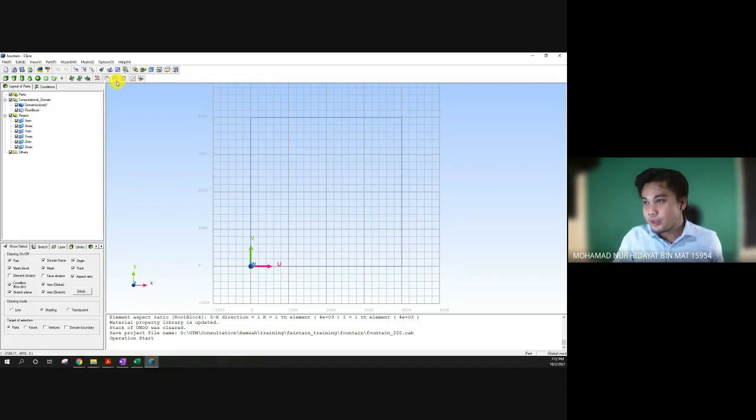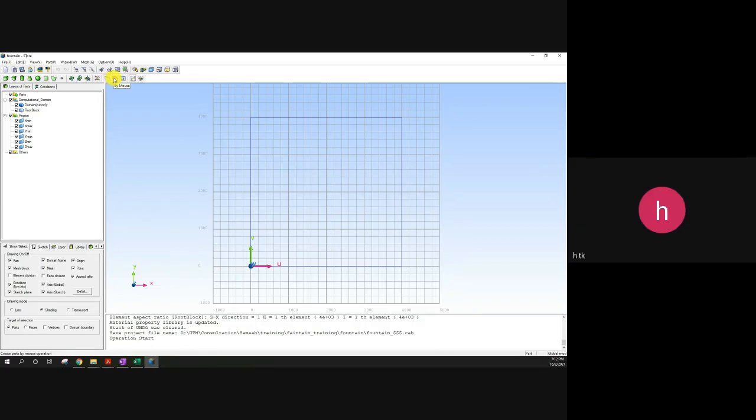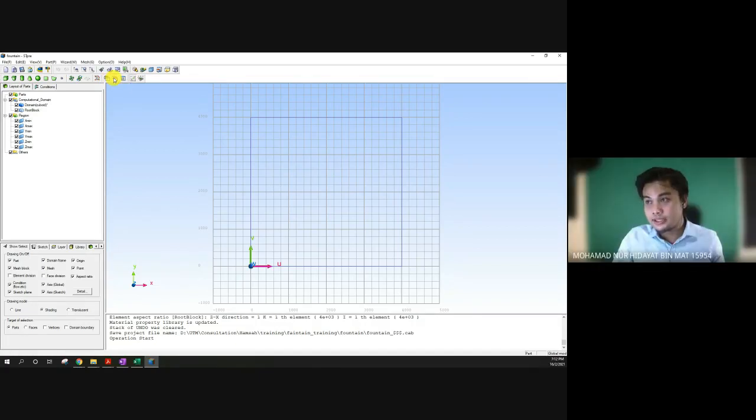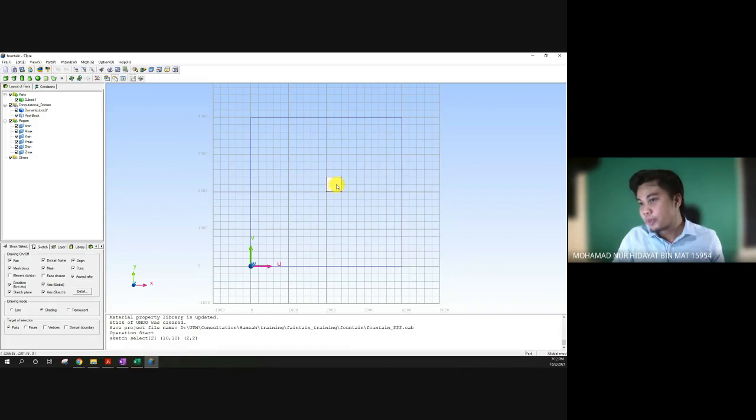So what do you need to do? You click here by mouse. We can create the geometry by dialog, you just need to fill in the coordinates. However, I don't know the coordinates, I want to assign manually. So you need to use the by mouse setting. Click by mouse setting, and then click here, cuboid, and then click somewhere else here. So this is your first geometry.